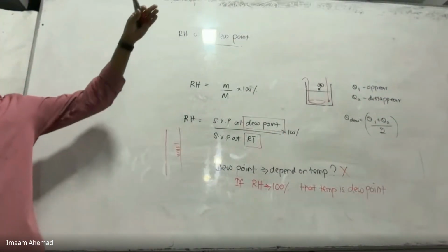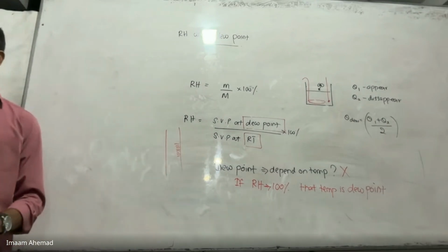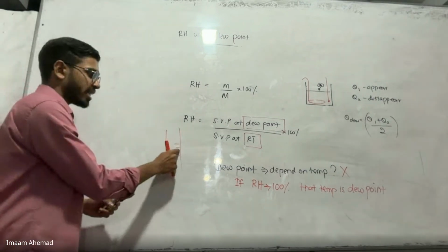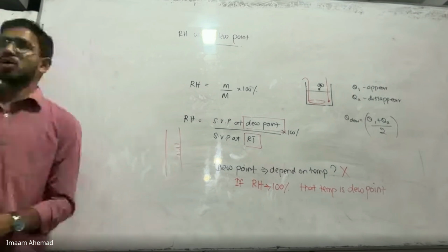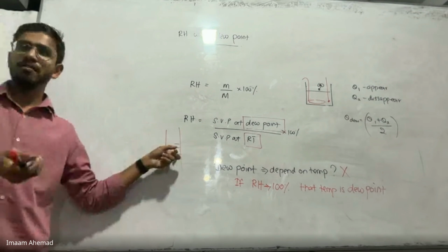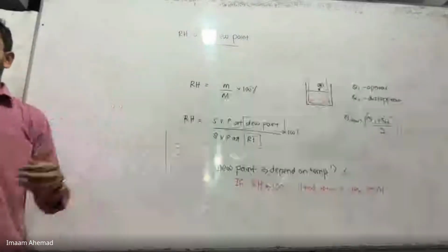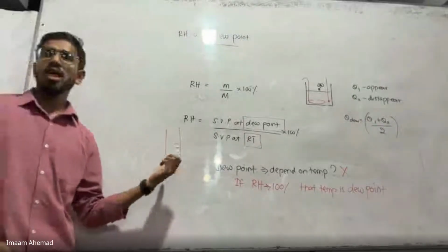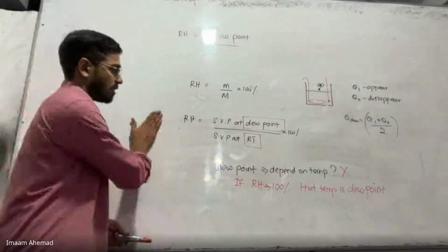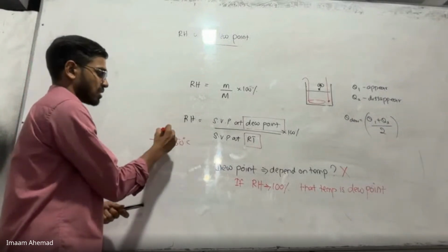If it has to measure a huge range, the calibrations will be very close. But if it has to measure a smaller range, then there will be a better gap between them. So this thermometer is more sensitive than the one that has a higher range. Obviously, the one that has more sensitivity is better. So we can use the thermometer with minus 10 to 50 degrees Celsius.